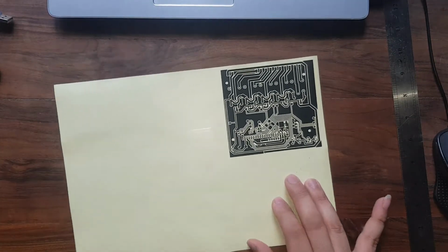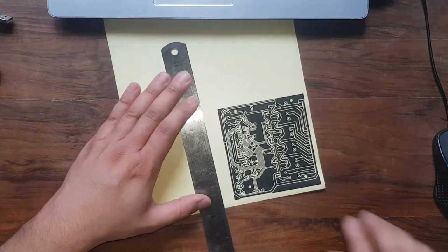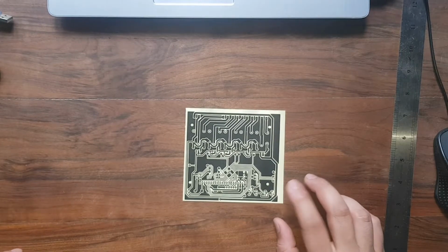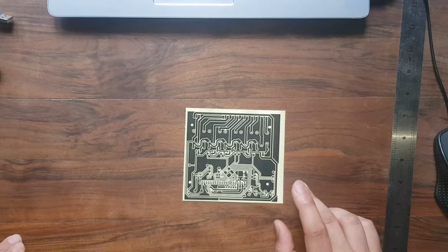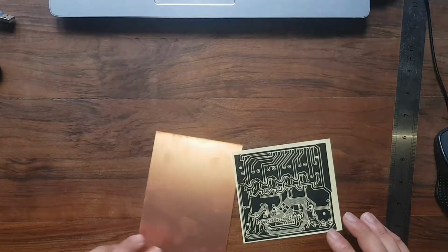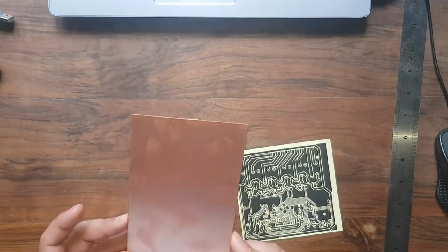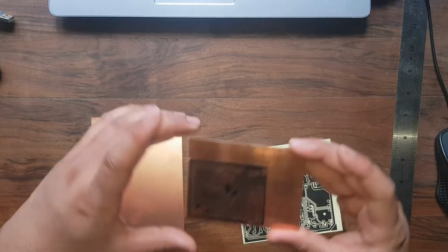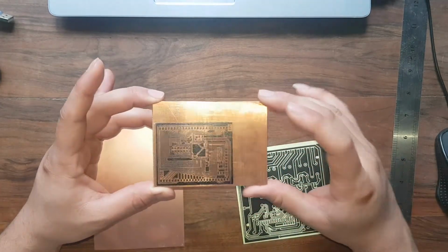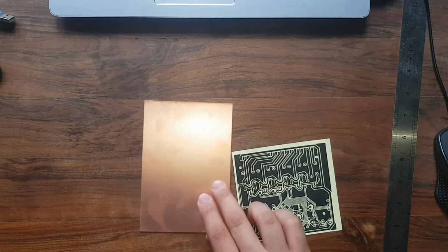Okay, I just printed. I'm going to cut it. Of course, the quality of your printer is really important for the quality of your PCB. And about your PCB, you have to sandpaper your PCB so it will become shiny. Don't use one that is oxidized, it's not good. You're going to face some problems along the way, so just use a shiny one.